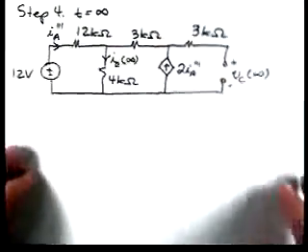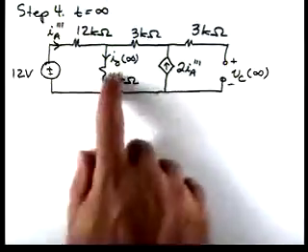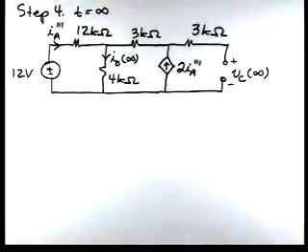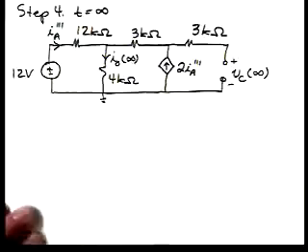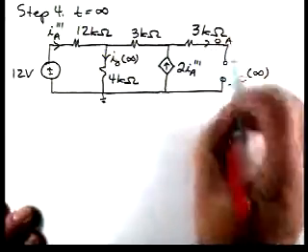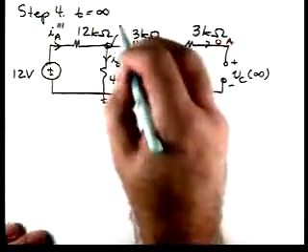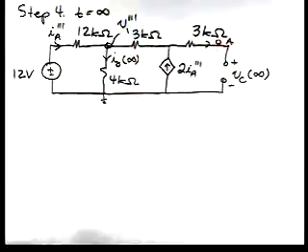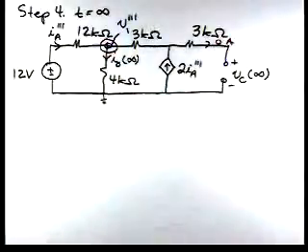Now we're going to assume the circuit's in steady state again. The capacitor is replaced by an open circuit. And again, we need to find I0 of infinity. I'm going to select this as a reference node. Again, we note this is 0. We have one node voltage here, V1 triple prime, and what we'll do is apply KCL here and come up with a nodal equation.